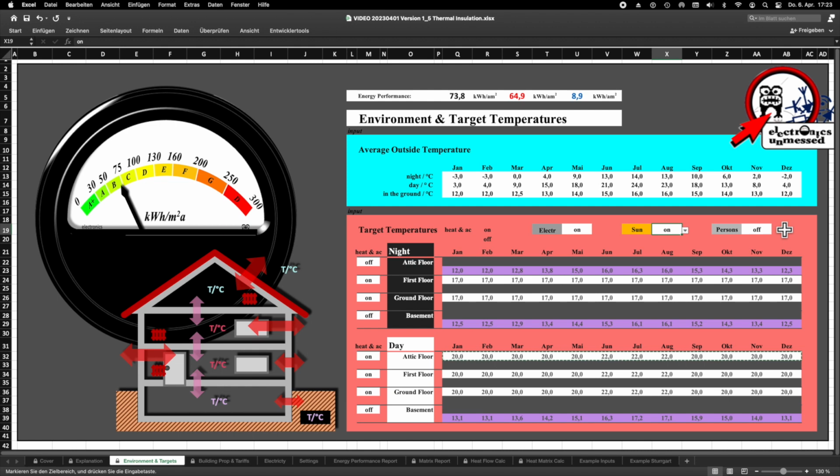A human gives off around 60 to 100 watts of heat power. With our switch here, we can take that into account or not. This would theoretically save us a few more kilowatt hours. In practice, however, ventilation is also required when people are present, and as a result the energy is lost in cold climates. In a hot climate, it is even double counterproductive because you have to ventilate more and you need to compensate the waste heat from people as well.